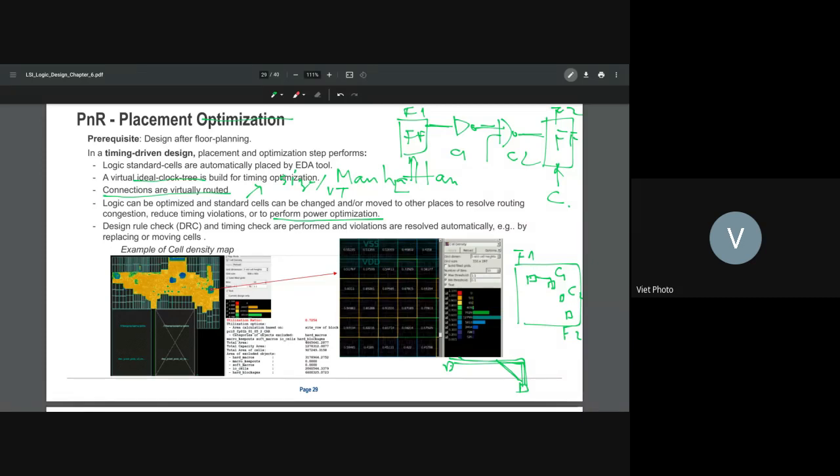Design rules for the routing are like the minimum width, minimum spacing, the minimum via, or the end-of-route rules, or the rules for metal 1, metal 2, metal 3, and so on. The rules are so complicated that checking the DRC takes hours, even more, maybe half a day or something. So during the placement, we do not really try to fix the DRC.